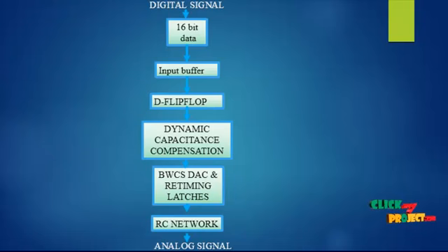This single data input, labeled D, is used in place of the S and R signals, and is thus called the data input. If this data input is held high, the flip-flop would be set, and when it is low the flip-flop would be reset.